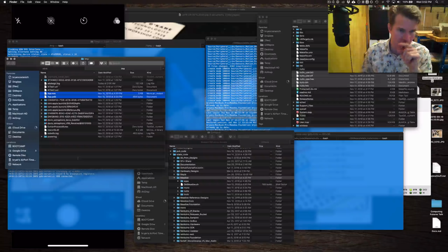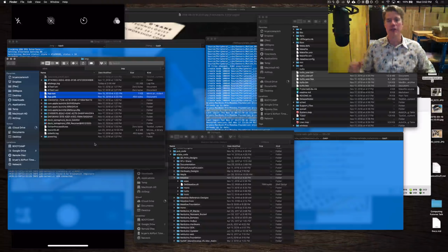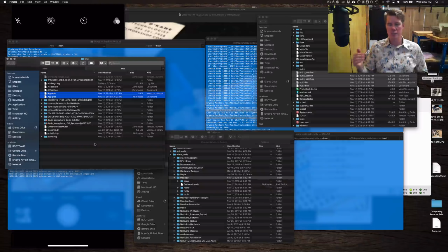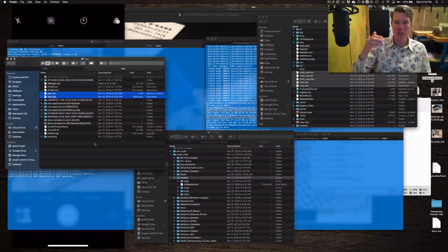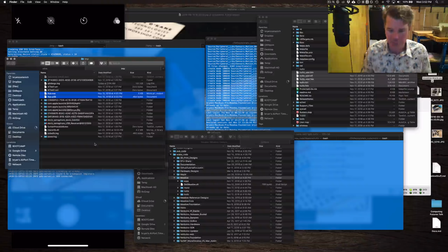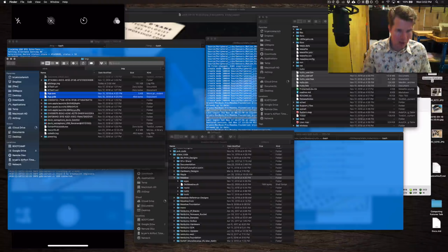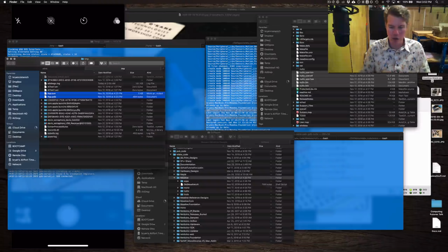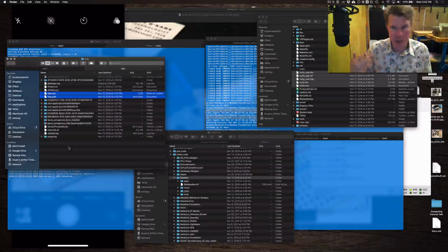But the other thing that we can do is build our mono application. We just drop it in the temp directory, and then we load it from there. So the board boots into Meadow, and then it will go and load the application from the temp directory. That allows us to deploy apps faster, because we don't have to flash it every time. We just have to reboot the board, and it'll load whatever apps are in there.